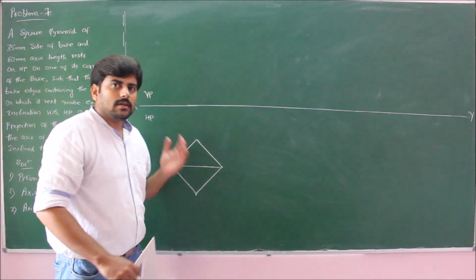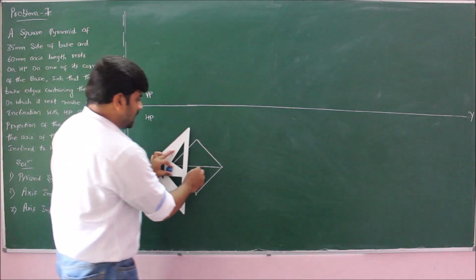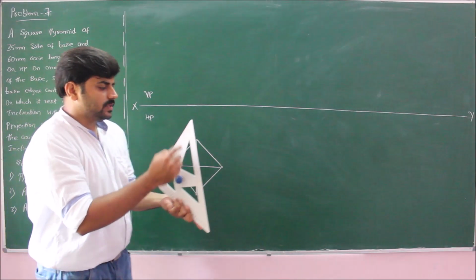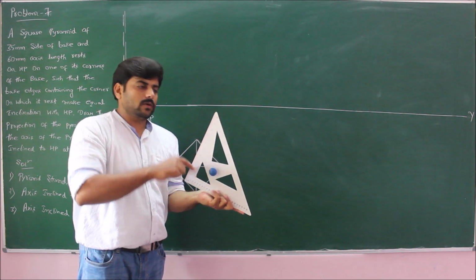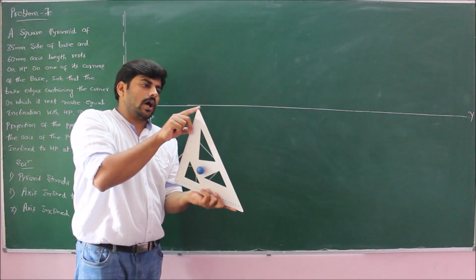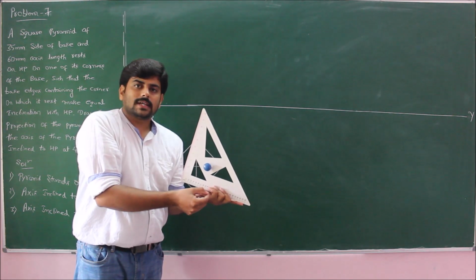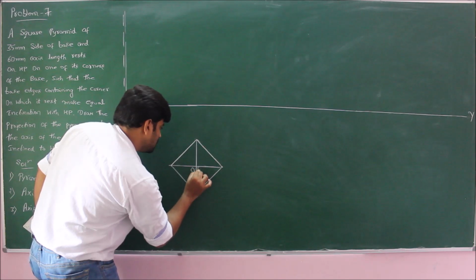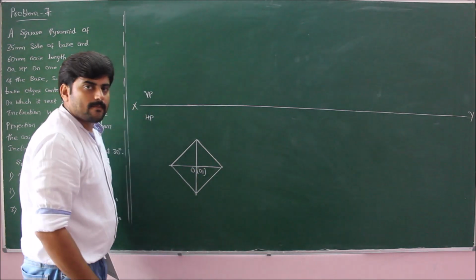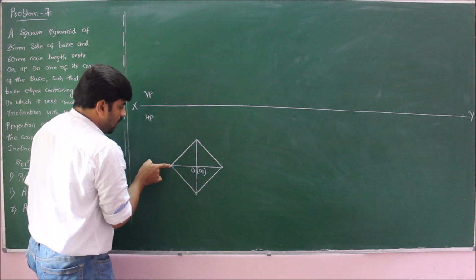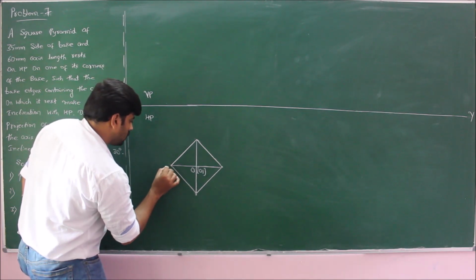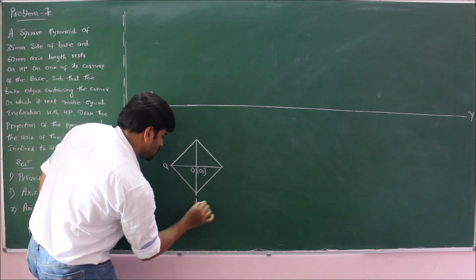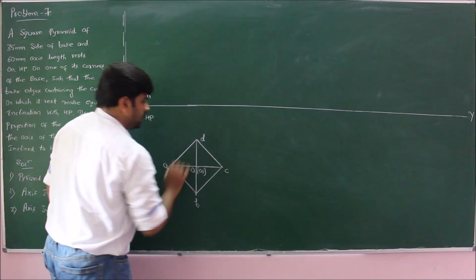Since this is a pyramid, to the center draw dark lines from all the corners. Now if I view the pyramid in the top view, I can see the top of this axis whereas the bottom of the axis is invisible. Therefore, O is visible, O1 is invisible. Coming to the corners, all the corners are visible to us. Therefore, we have A, B, C and D.